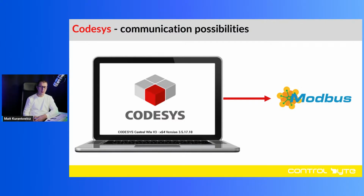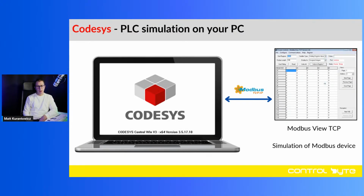This is a real-time simulator, and you can create a program for Modbus. On your computer, you can test your program and PLC simulation, and you can connect with, for example, a tool, Ocean Controls Modbus View TCP, and you can simulate a Modbus device. Thanks to that, you can solve a lot of examples and understand how Modbus works.